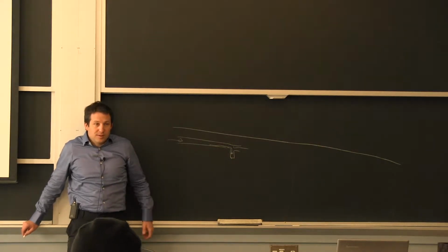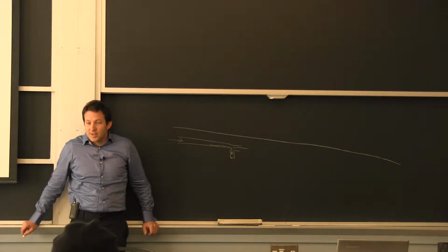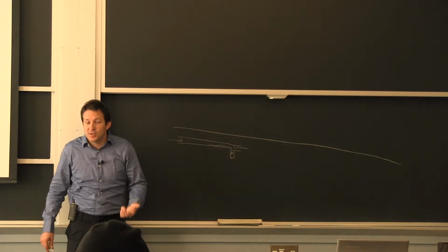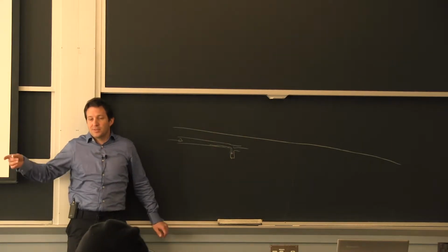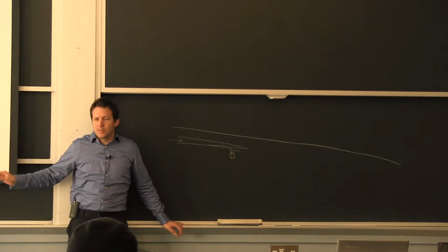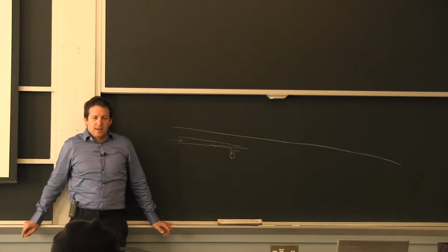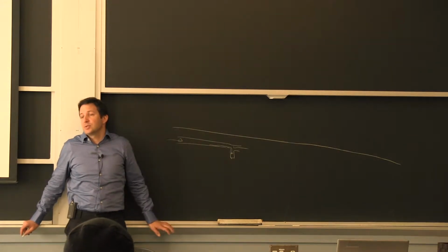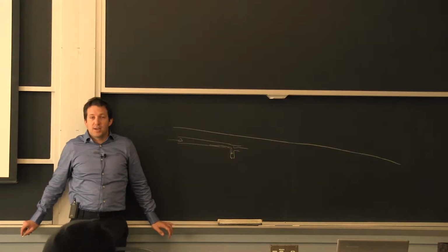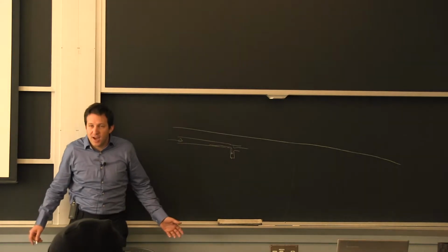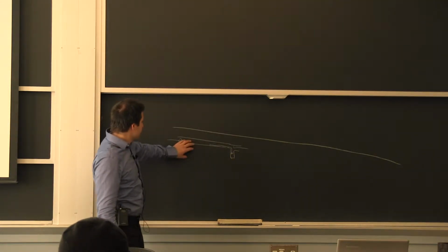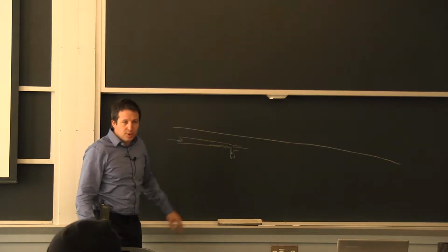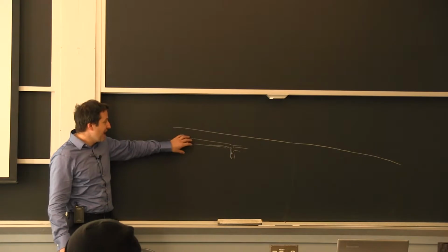So if you have welds there, that's why you need a factor of safety of 5. Because we're not talking about something that will happen 10,000 times. If you remember from yesterday, those graphs at 10,000 cycles, it's still sort of okay. You have a good capacity. So we're not talking about a million times that this event will happen, but maybe thousands of times. And that's why we have what we call the factor of safety of 5 between the pressure that is normally in the pipe as opposed to the capacity of the pipe for hydrostatic pressure.